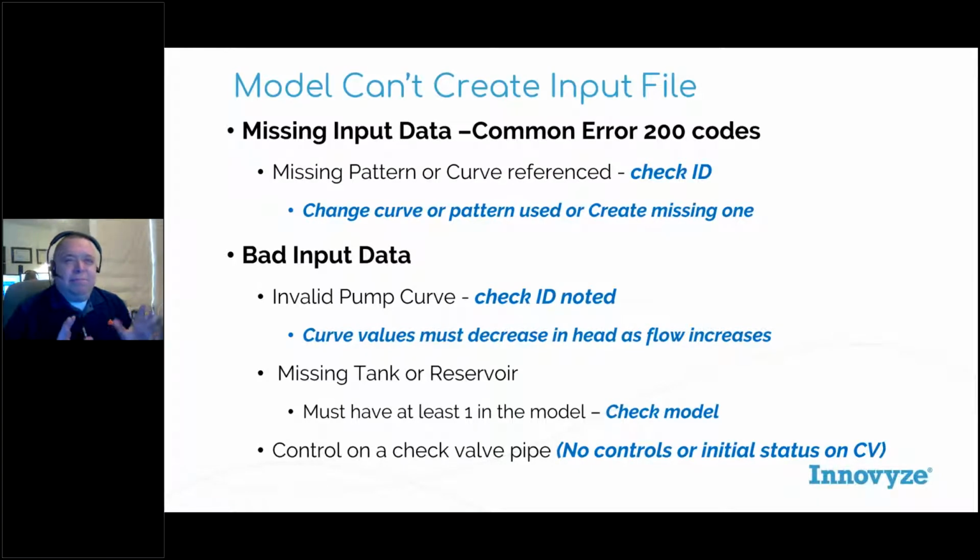And so there's some, I think they're usually vertical turbines, that you might have a slight rise before it continues down. So you just have to cut off that rise so that all the values are going down. Generally, your pump's not operating near that point where that rise is, so it's not a big deal, but that's something that EPANet cares about, and InfoWater and InfoWater Pro do too, because that's our primary engine.